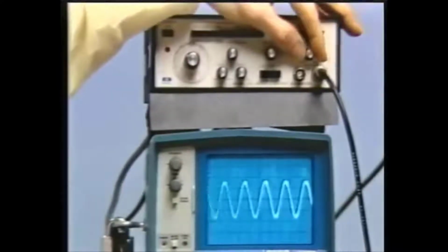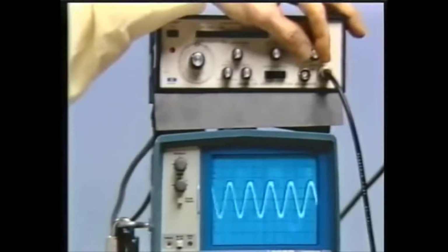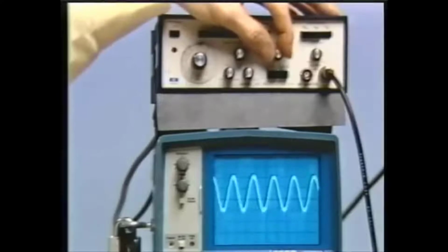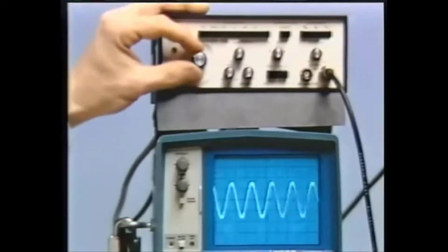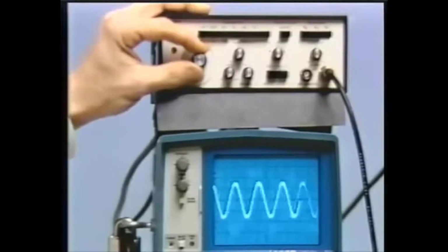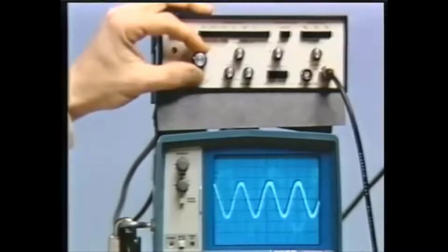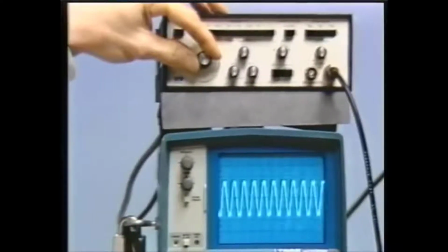By varying the amplitude knob, you can make the sine wave smaller or larger. Ear isn't too sensitive to that. By changing the DC offset, it simply rides on a different level. It's like putting a battery in series. And changing the frequency, you get a very perceptible change. A lower frequency, it takes longer to sweep through a period. Higher frequency, it takes a shorter amount of time.